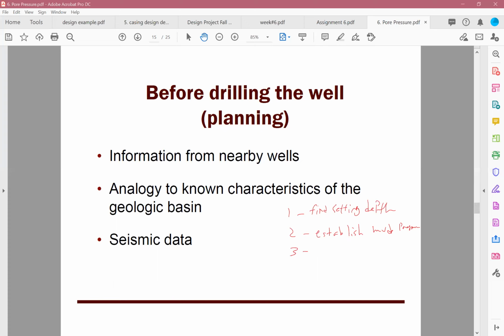Then you start to design your casing, right? So design casing for each section of the wellbore that you are designing, from surface, intermediate, production separately. And in the design, you do the burst first, right? Then you do the collapse with all those equations. Then you do the tension, and you are done. Okay, so this is basically the general procedure that you would do for designing your casing. In your project, you do all these steps. In the extra point homework, you only do the design part.